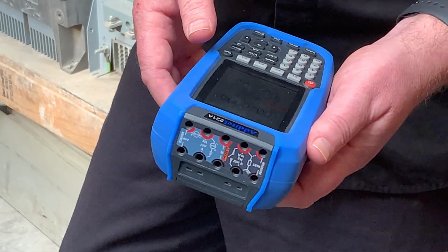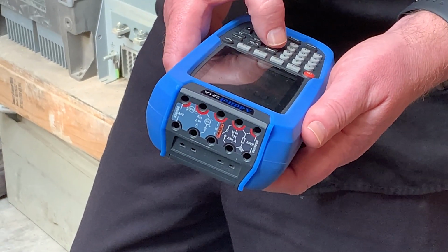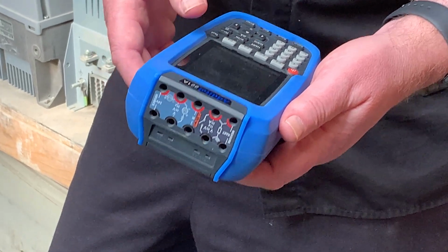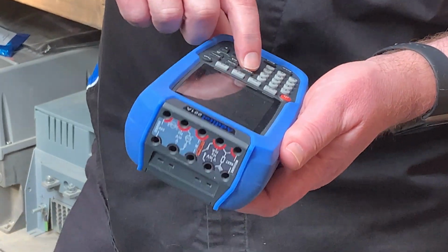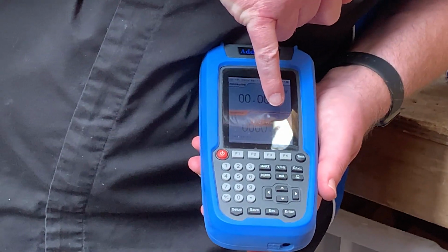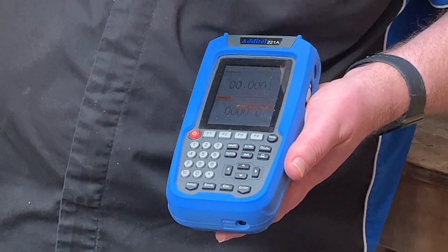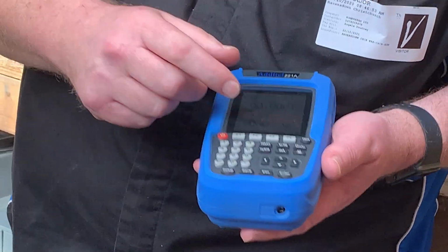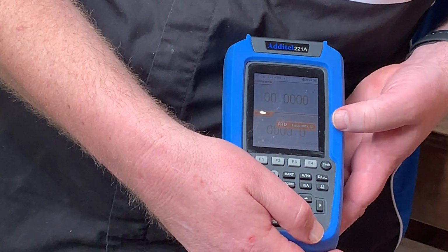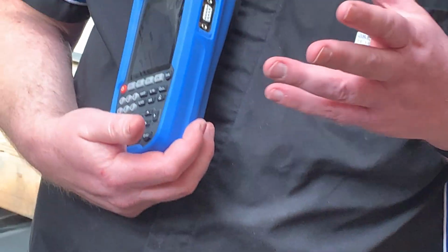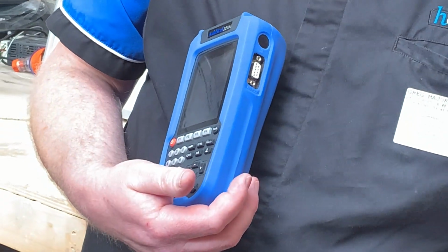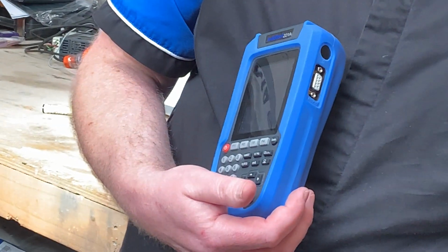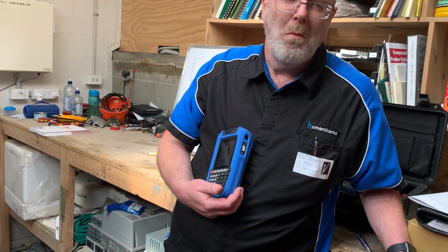Why don't you just go to RTD? That would be the other way to do it. Yeah. Same thing. And the advantage of going to RTD is that it's got the various different curves, because not every RTD is the same. In this case, we have an RTD 385, which means it's 0.385 ohms per degree C. There are other curves of RTDs. Again, 99% of the time, yes, you'll be using a PT100 with a 385. But very occasionally, you might come across a PT100 with some weird curve, and this covers it as well.